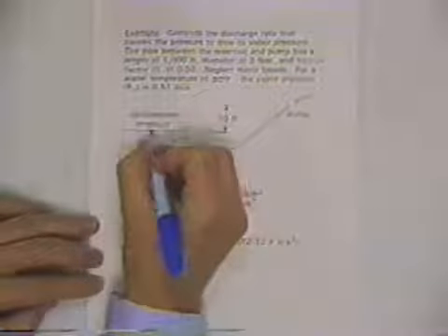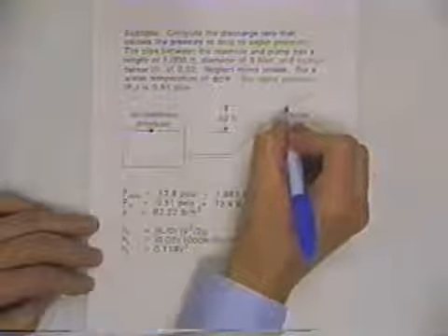Okay, so the energy equation comes into play again. We use it a lot in fluid mechanics. And we pick our two points, and we always pick the two points based on our ingenuity to solve the problem. So let's pick a point here. We know the pressure head there. And let's pick a point here. We had to use a bit of ingenuity to recognize which point in the system would have the lowest pressure.